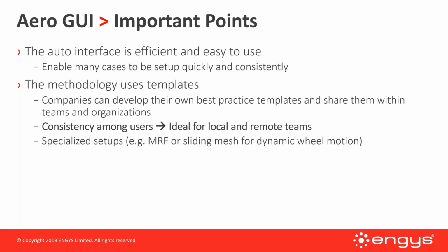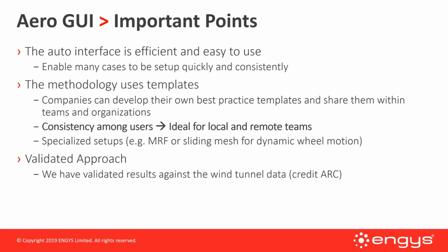So the methodology uses templates. Companies can develop their own best practices and share them within organizations. The important thing is that there's consistency among users. So this is ideal for local and remote teams. And it's very easy for one engineer, one group of engineers, to set up templates and share them with each other or share them with another team. You can also do specialized setups with multiple reference frame or sliding mesh for the wheel motion.